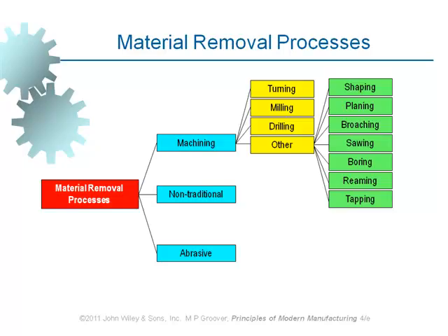If we want to improve the accuracy of the size of the hole, and also the surface finish of the hole, then we've got to make use of another tool which is called a reamer. Reamers are used in order to improve the quality of a hole which is already made by a drill bit. So first we've got to make the hole, then we apply a reamer in order to bring it to the actual desired size.